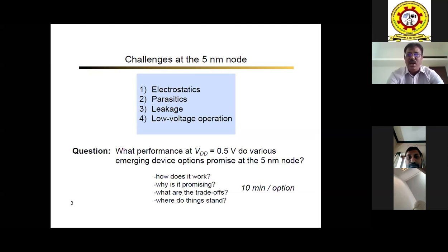So now that 5 volts has come down to 0.5 volts. VDD of 0.5 volts means the 0.5 volt level is considered digital logic 1 now. And of course, digital logic 0 still remains at 0 volts. So now the difference between logic 1 and 0 is only 0.5 volts.